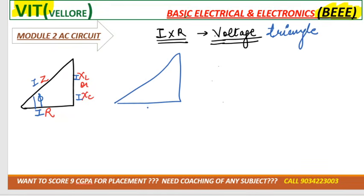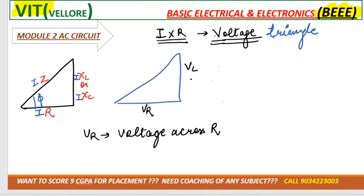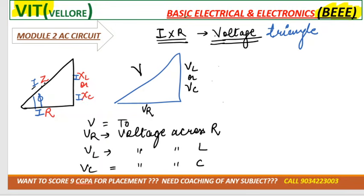In the voltage triangle, on the base we can take VR, right? VR is the voltage across the resistor. On the perpendicular we can take VL or VC. VL is the voltage across L, VC is the voltage across C, right? Here V is the total voltage, because total current and impedance is the total combination, right? V is the total voltage. Understood? So what we got, the formula: